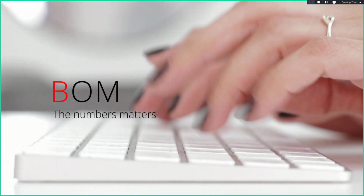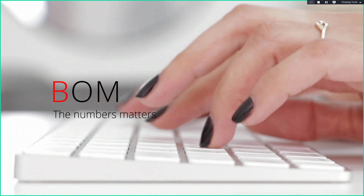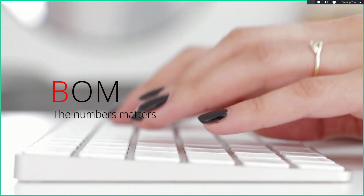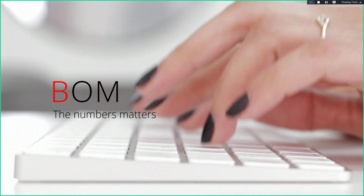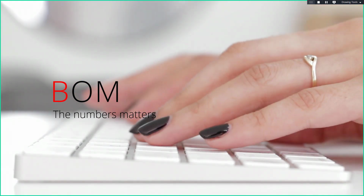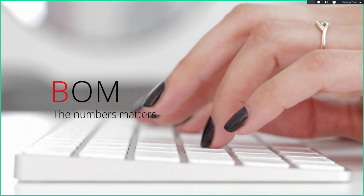Now, this model is completely defined, and we can move to the next step. Since the model contains all the information, the materials, the hardware components, and we defined the grain direction, oversizes, and so on, now we can go for the next step, which will be bill of materials generation. Those of you who don't use automation tools know how long it takes to make a BOM, a bill of materials. This is a very routine process, prone to errors and so on. So let's take a look at what we made here.